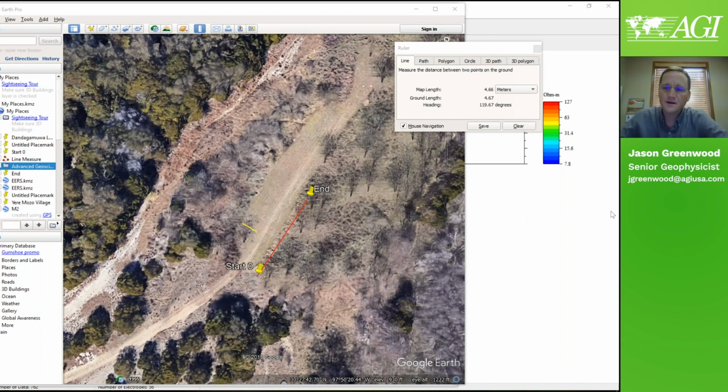Yes, there's a logging function built into the SuperSting menu for short-term time lapse, in that you wouldn't want to leave it out to the elements with the cables exposed. Typically for time lapse that's going to go over several days, you need to protect the cables from rodents or anything that may go on site and chew on them.